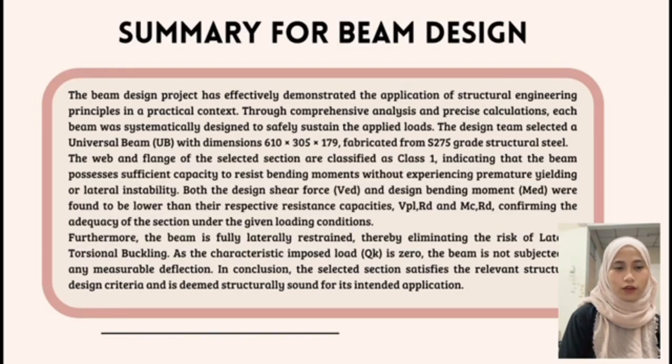The web and flange of the selected section are classified as class 1, indicating that the beam possesses sufficient capacity to resist bending moment without experiencing premature buckling or lateral instability. Both the design shear force (VEd) and design bending moment (MEd) were found to be lower than their respective resistance capacities, Pv,Rd and Mc,Rd, confirming the adequacy of the section under the given load condition.